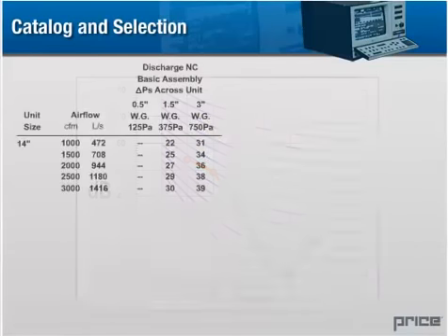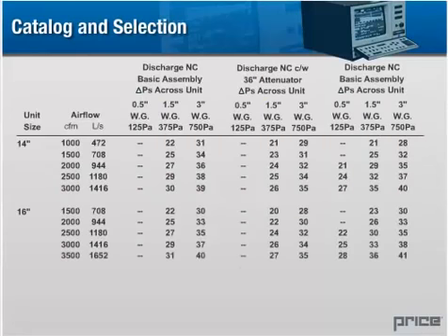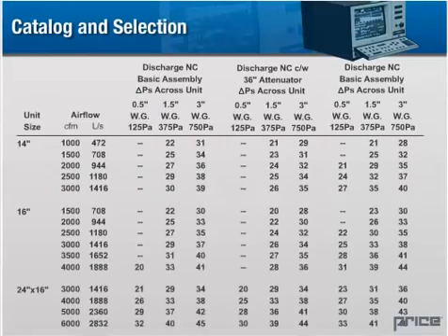Because we have sound power readings for various airflows and pressures, we can produce NC ratings that correspond to each of these combinations as well. This is a portion of a typical chart found in the price catalog, which shows NC levels for a terminal unit under various conditions. Dashes are shown for circumstances where the NC level is less than 20, since the noise contribution would be so quiet as to be imperceptible in most settings.